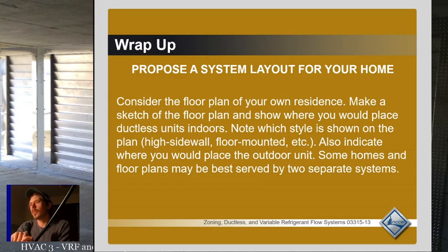Because you want to be able to move the air from one side of the room to the other. Now, you don't want to do that directly. You don't want it to be too high of a velocity as it's doing it, but at the same time, you need to be capable of throwing the air that far. In houses where you're doing a lot of mini splits on a large footprint, a large floor plan, it can be very difficult at times to get enough flow that you're properly circulating the air.